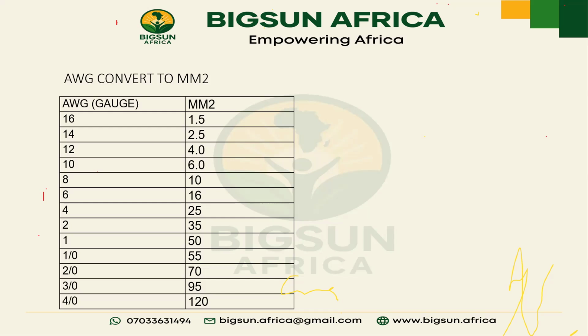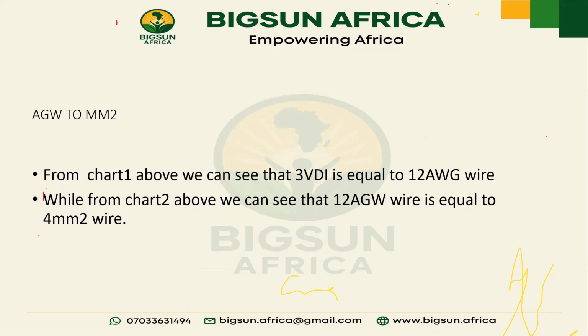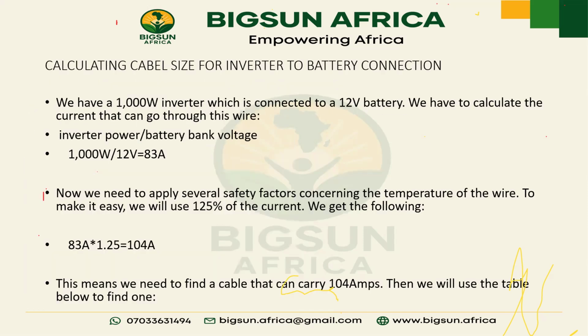Even as much as we think that the negative doesn't carry much load, you need it to complete your circuit because electrons flow from cathode to anode, right? Yes, sir. It's the returning part. Yeah, the two of them have to be the same size. Okay, no problem. So let's look at our breaker sizes now.